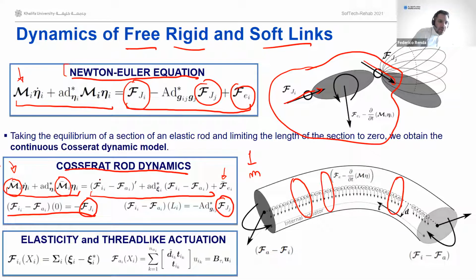Now, how can we model the internal forces? There are generally two kinds of internal forces: elasticity forces, and here, for instance, is represented a linear Hooke-like relation. However, in fact, any constitutive law can be applied here, for instance, such as the one that Matteo presented to you, I think, yesterday.